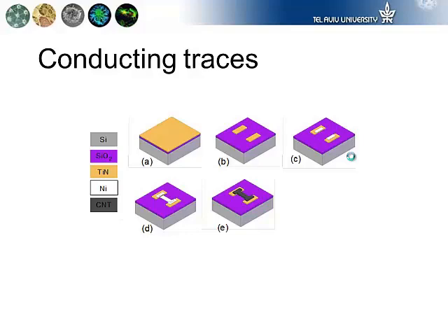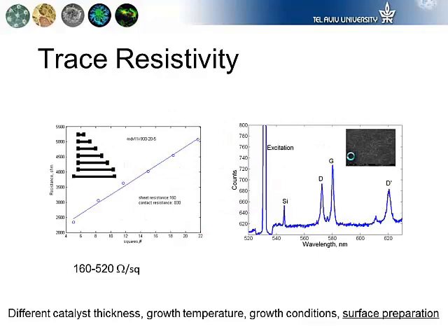In order to validate the electrical conductivity, we made these test structures, and then we can systematically do the electrical measurements and validate the electrical resistivity. And in this particular application, it doesn't look like extremely fantastic values, but for this application, this is more than enough, considering the fact that you're limited by the interface impedance rather than by this resistivity.